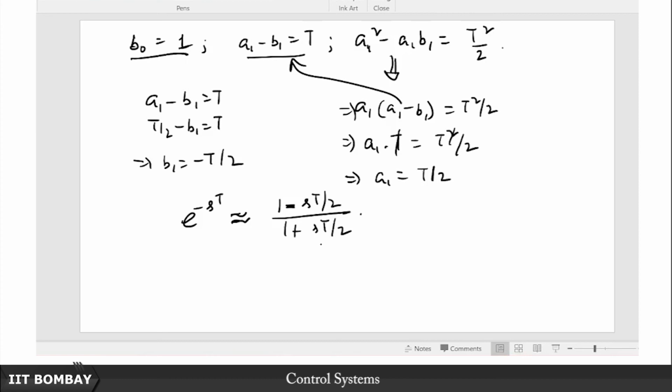Therefore when you put them in closed loop configuration, you will always have the gains migrating to the right half plane at some point. Yeah, so that is something to be wary of. So that is the reason why this complementary root locus assumes a lot of significance. It's more important than maybe it's made out to be in many textbooks, where it maybe gets just a passing mention. But I think that it's worth our while to go through all of this, maybe not me in this course, but you should definitely make it a point to go through all of the points that we've discussed about root loci and apply them to complementary root loci by using that modified angle criteria.